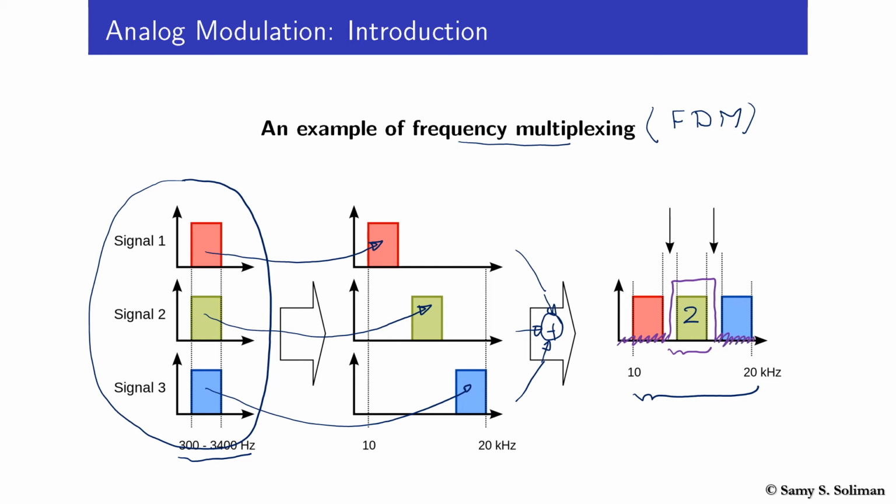So this is called multiplexing, the simultaneous transmission of more than one signal. What we have achieved here is that we used a single communication channel to transmit more than one signal simultaneously. However, for that to be useful, we must have a way to separate them back again at the receiving side, and here we performed frequency division multiplexing by translating each signal to a different higher frequency so that we can separate the multiplexed signals using bandpass filters.